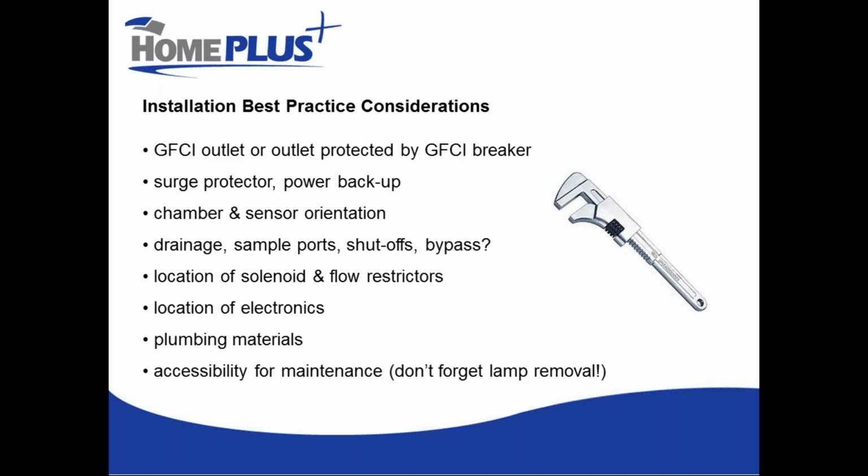We don't want to have long lengths of pipe, and particularly around corners and such, where microorganisms might be able to swim past the UV chamber into that downstream line before it reaches the physical barrier of the solenoid. Microorganisms, given enough time and a long power outage, can definitely move around in the pipe there.